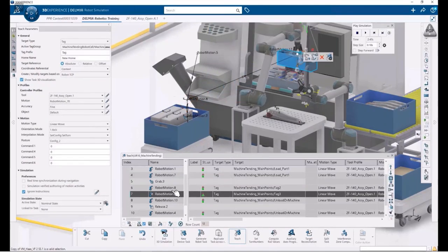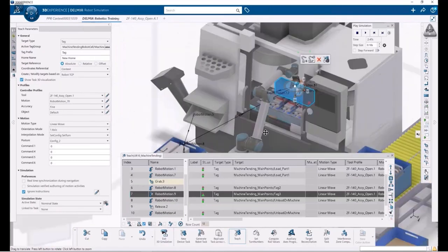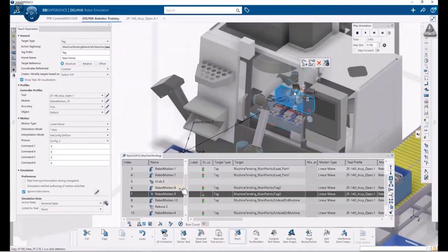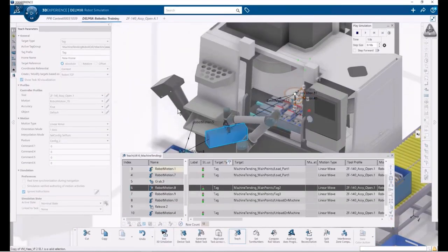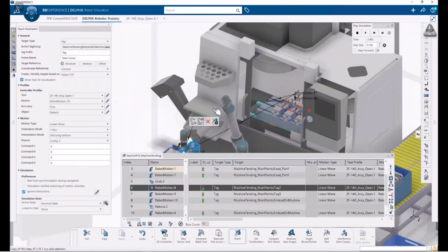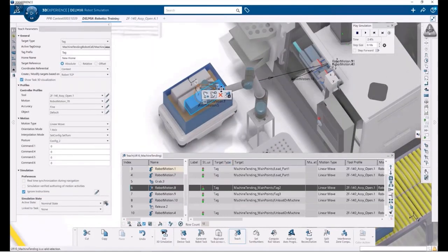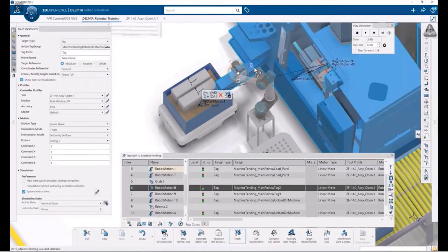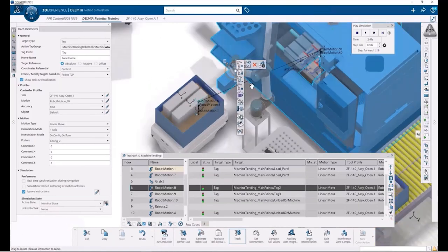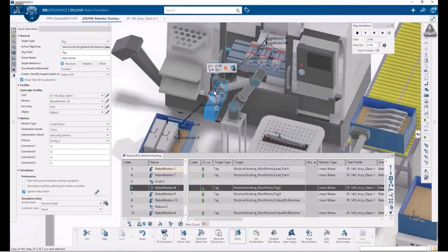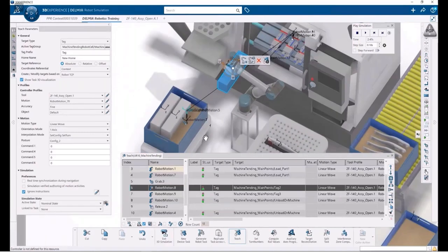So right there, I saw that the door turned blue, which is because when it is moving from the retract point to the drop point, the raw material is clashing with the door. So this is an excellent tool which allows me to do all the validation even before creating my final program. So I'm going to add an intermediate position in between so as to avoid that clash.